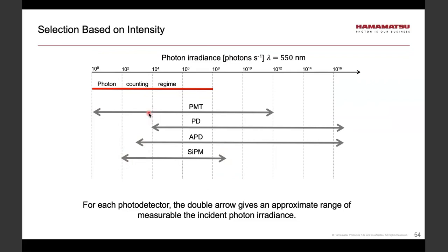What choice I ultimately make will depend perhaps on other considerations. If the light level is sufficiently high, even though there may be multiple choices, one typically will go with the photodiodes. If you have plenty of light, photodiode is an excellent choice.